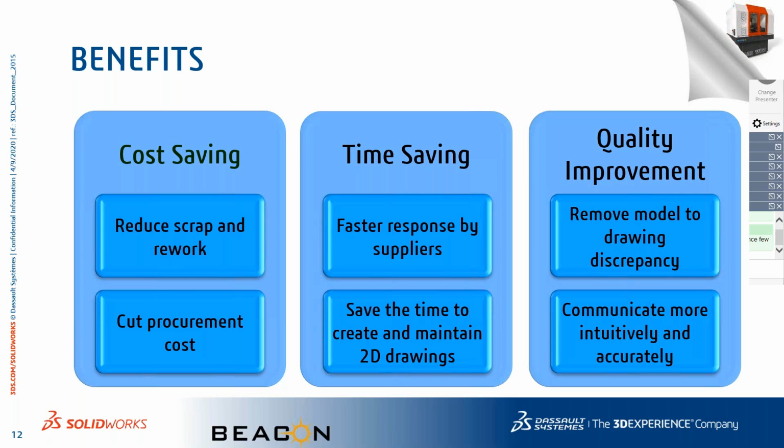One more thing I just wanted to tell you is that we have the option of even publishing this in STEP 242. I think this is one of the most important things to most of the manufacturers who are going for integrations of CAM. So you can directly give the STEP 242 and send these models to your manufacturing shop floor persons, and they can use it for their benefit.